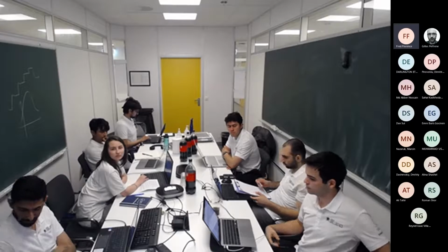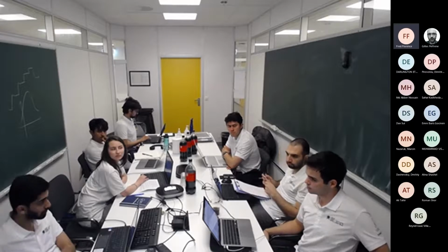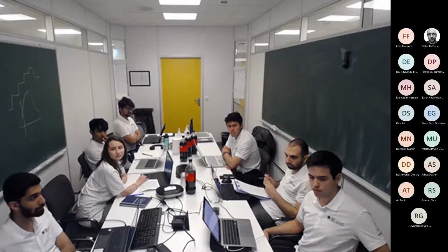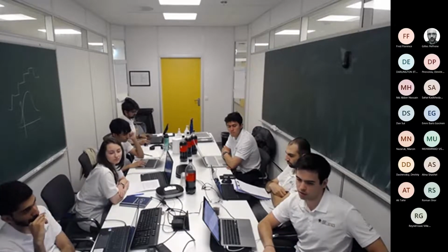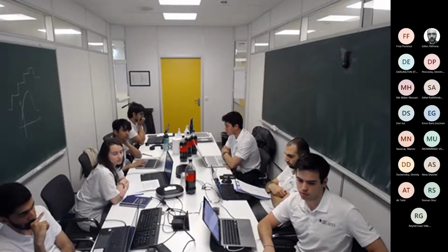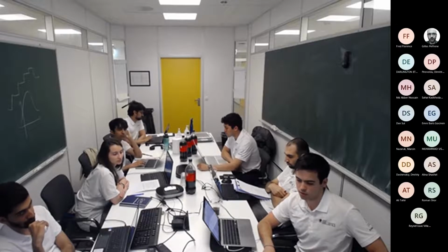I had a question. You do some pressure calculations and you iteratively start from the bottom up. Why do you do that? The bottom hole pressure calculation, you mean? Yes. We follow the shooting method. So we suppose that we have a bottom hole pressure at the end of our well, let's say at 2,000 meters. And then we have a liquid flow coming from the mud at the end, and calculating node by node